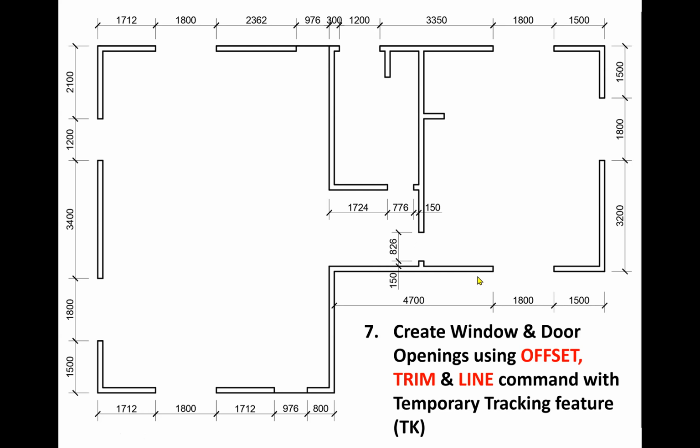Okay. So if you want to know what the size of the doors for each opening, you would minus 76 and you will know the door. So this door won't be 826, it will actually be 750. When you take away 76, you end up with 750. The bathroom door will be 700 because we're going to be taking away the door frame size, which is 76, 38 on either side. All right. So we're going to offset 976, make that be our primary distance since it occurs twice. And then we will override for the bedroom and override for the bathroom.